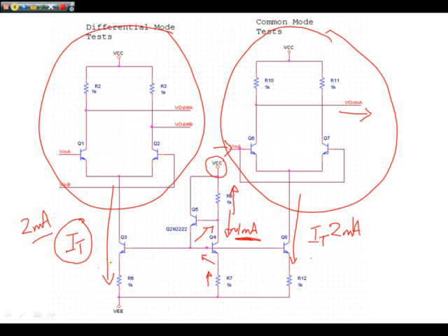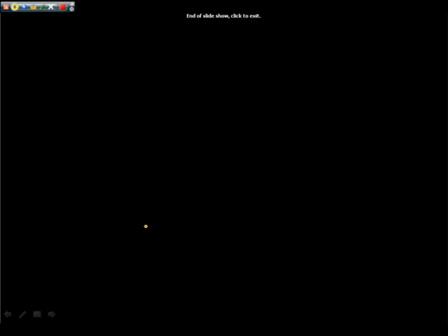As there are two outputs in this case, what I would do in my design parameters, I would make sure this is perfect, exactly 1 milliamp, and then I would make this close to 2 milliamps, and then I would optimize this component down the bottom. And then I would do the same thing over here. So I'm going to make this perfectly 1 milli, and then this perfectly 2 milli, and this one perfectly 2 milli. That's my design parameters. I'm not going to cover anything else. I think you should be able to do it completely by yourself now.